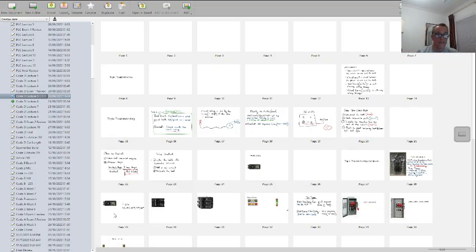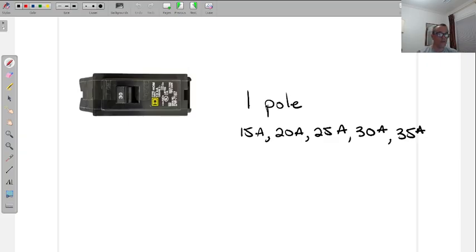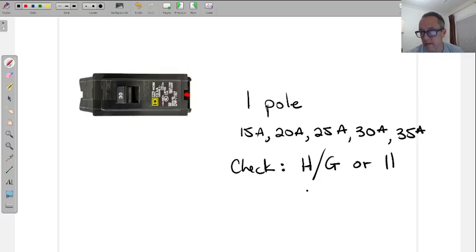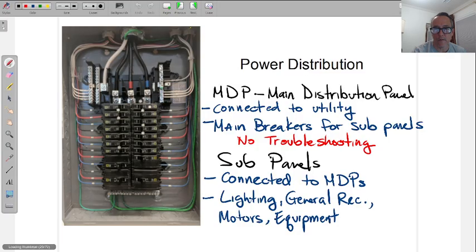All right, so that's one way that the breaker goes bad, because it can't hold the amperage. The other way the breaker can go bad is it's not giving you voltage on the output side. And to check the voltage, you just put the hot on that side and the black on the ground. Exactly, very good. Either one. When you check, you can check between hot and ground, or hot and neutral. Either one is fine.